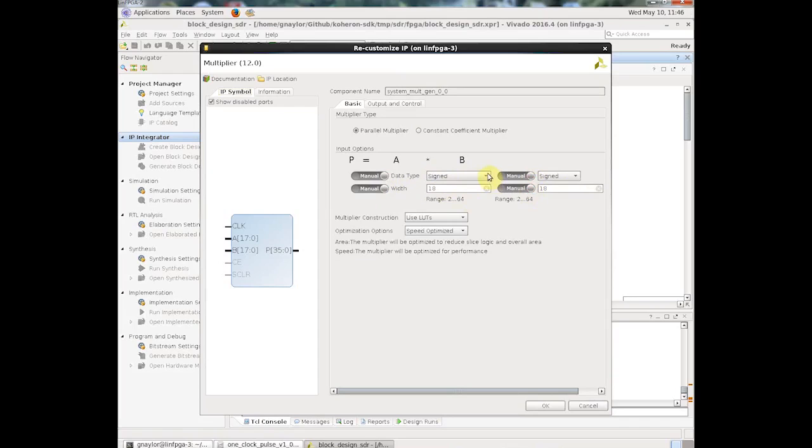So these values are assigned values for the local oscillator and the signal. Now the input signal is a 14-bit value, the ADC is a 14-bit ADC. We could use 18 bits, but I think 16 will be sufficient. We're going to derive that from a block RAM that we're going to cycle through to generate the sine wave. Okay, so that's all good.